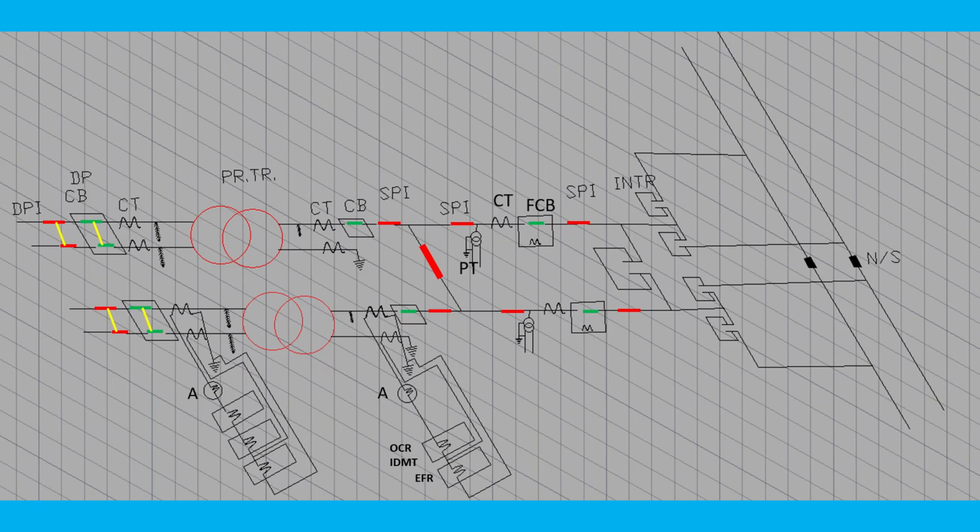But you have to study it thoroughly. First, how the current is flowing to the OHE. Second, the protection system: the instrument transformers, the protection transformer, and other protection like lightning arrester. Then some other protection for transformer protection.